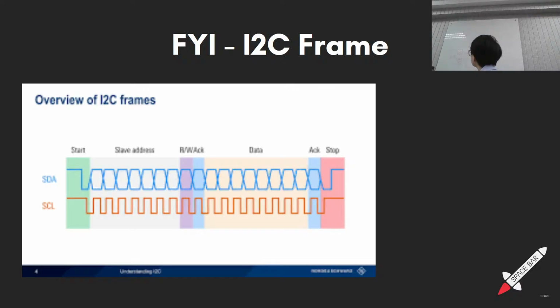And that's the beauty of open collector, because if let's say the device is misconfigured and this guy also pulls it down, so two devices are writing to the bus at the same time, that doesn't matter. Both of them are ground and nothing bad will happen.